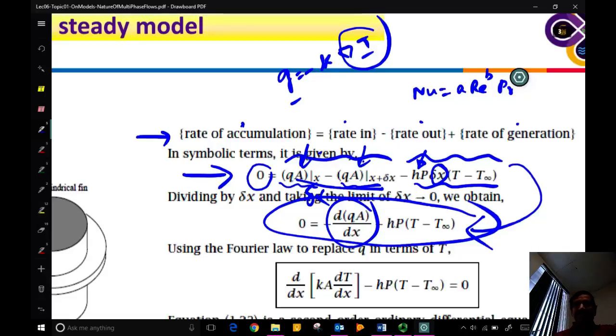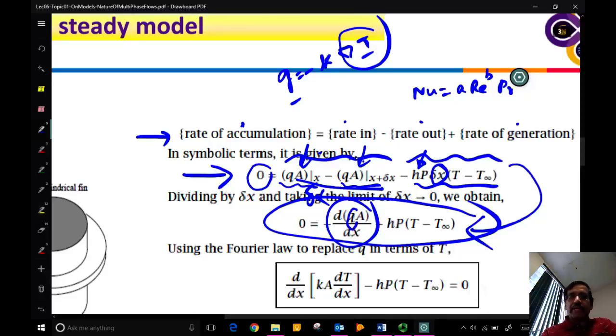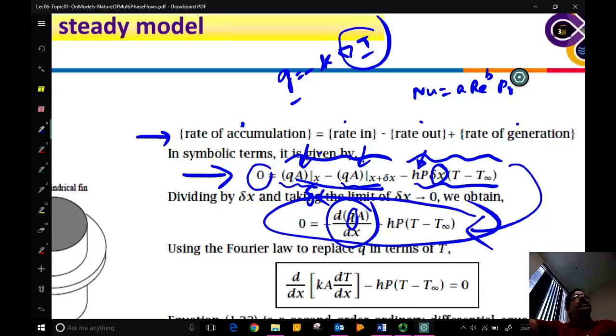But once you accept that empirical model for the so-called Fourier's law of heat conduction, the same thing is true for Newton's law of viscosity and Fick's law of diffusion. All these have a parallel in the sense they capture processes that are taking place at the molecular level. Energy transfer by conduction is basically by molecules vibrating, and they're not moving in bulk, they are staying in the same place, but they're vibrating and transferring the energy to the neighboring molecules, right?